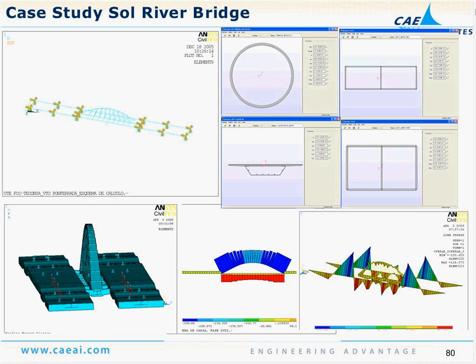So a beam model approach was used. In the upper left-hand corner there is the beam model. The columns were ignored in this particular model, just used as supports. The geometry of the various sections, there are some link sections. They're modeled with hollow pipes.